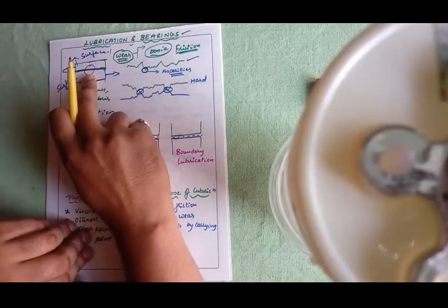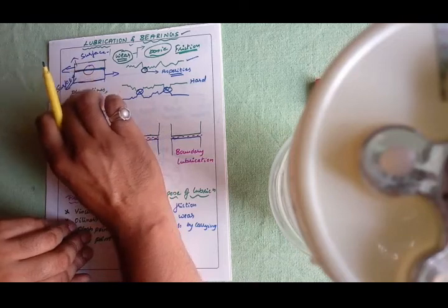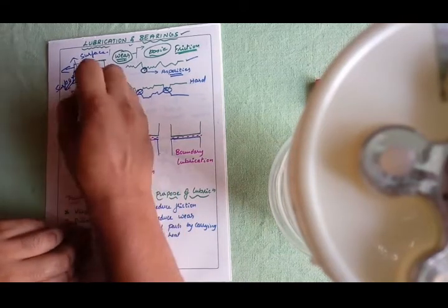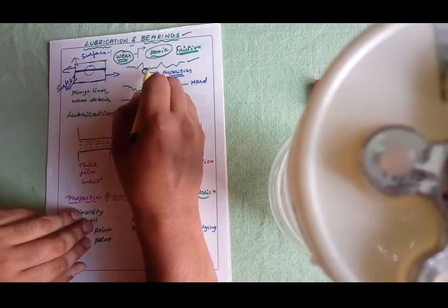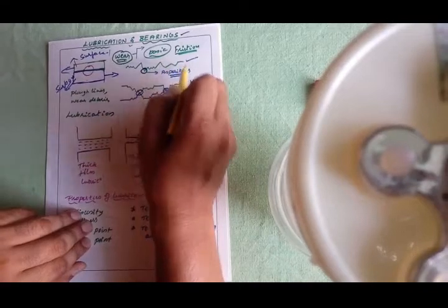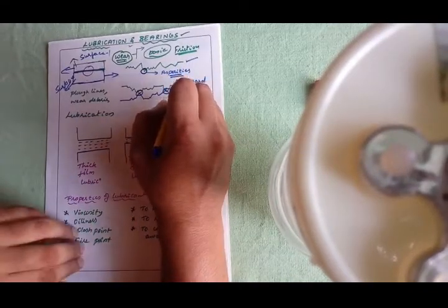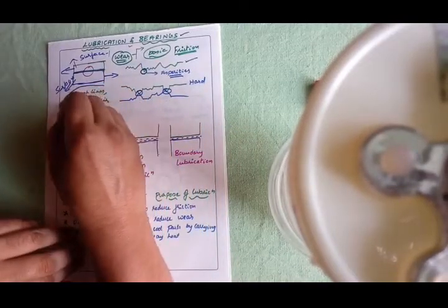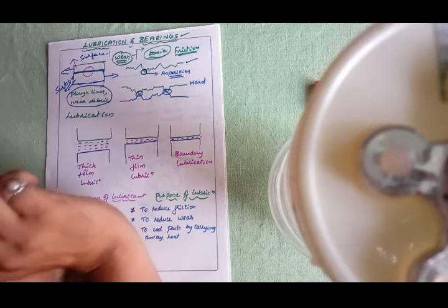Now, how exactly is the wear happening? If you want to understand that, first we need to look at the surfaces at a microscopic level. For example, if I focus on that surface in a microscope, you are going to get an irregular surface like this. The peaks of these irregular surfaces we generally call asperities. Now, whenever wear happens, it leads to flow lines or wear debris.